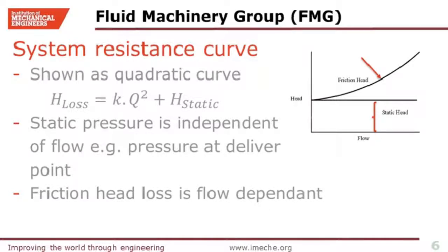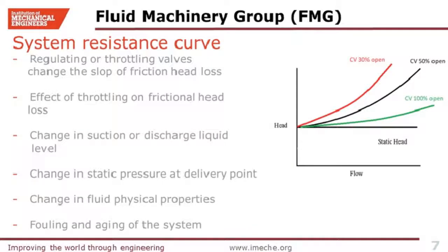The reason that we show the system curve in head, or say meters of water, against flow rate is because the pump performance curve also will be shown in meters of water. So it would be easier to compare these two together and discuss it in the next slide.